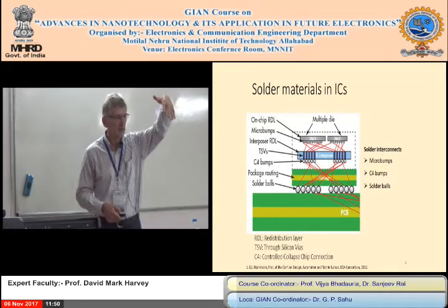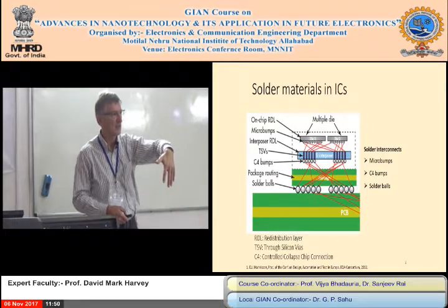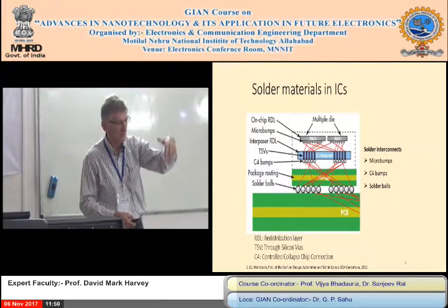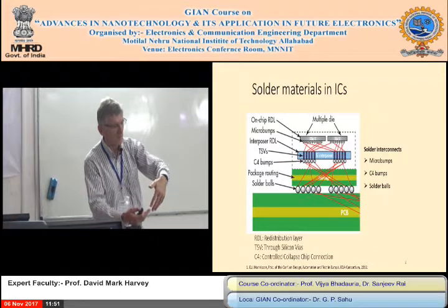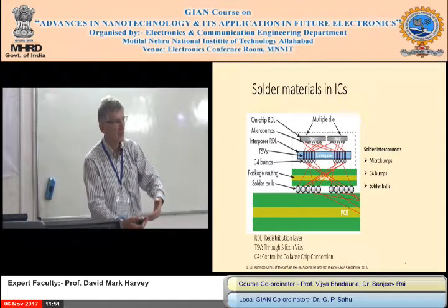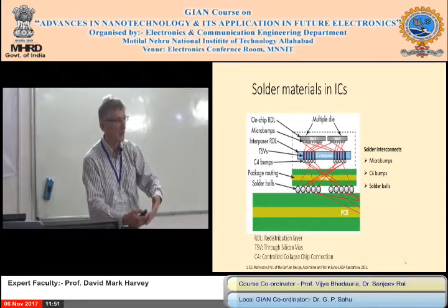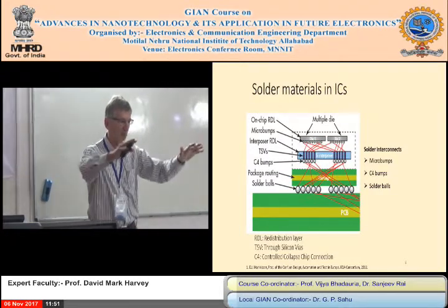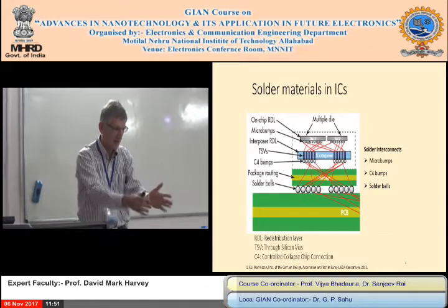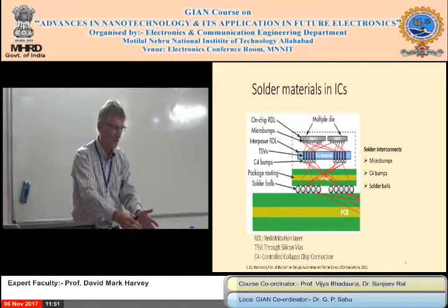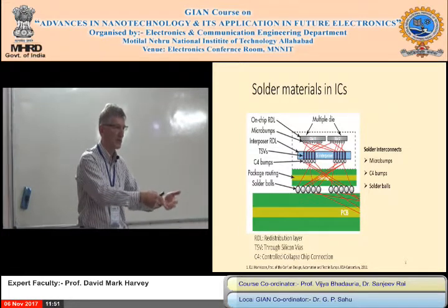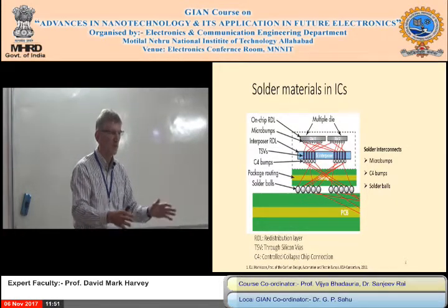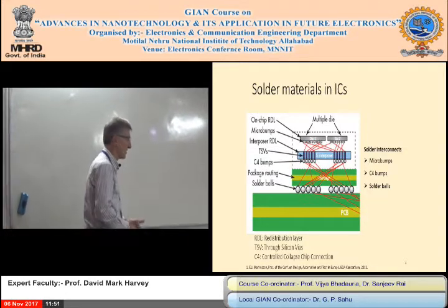Well, in the old days you used plated through holes. Have you seen these? And it's nice to make as a hobby. You drill the board with the holes, you make the circuit board, you solder it on the reverse side. Quite difficult to make when it's automated. If the chip comes bowed out, you have to put it through a process to bend it so it's parallel, insert the chip into the board, and the automatic soldering wave machine will solder it. Anything goes wrong, the chip gets bent or it gets misplaced, a lot of things can go wrong. But it's easy to test.